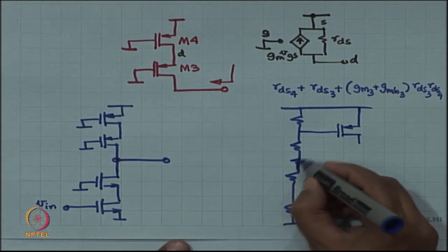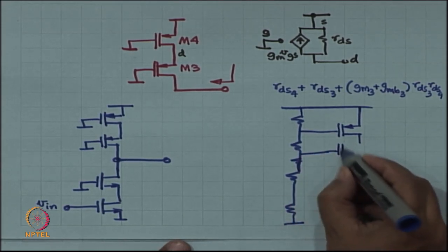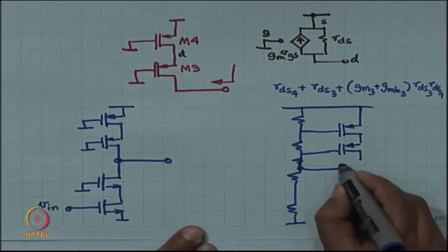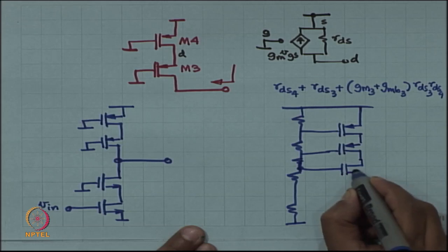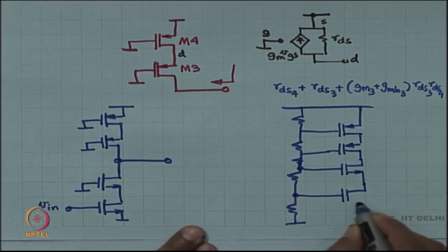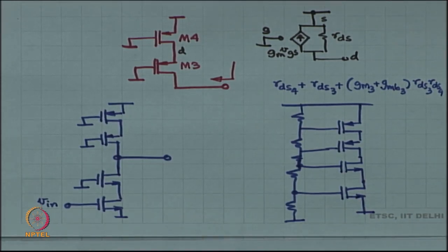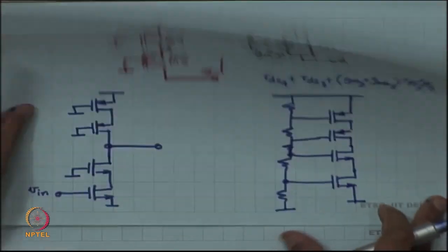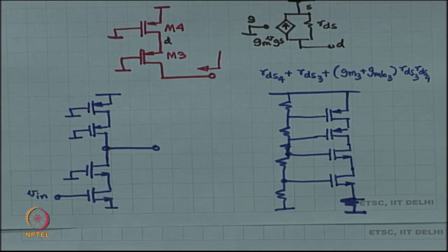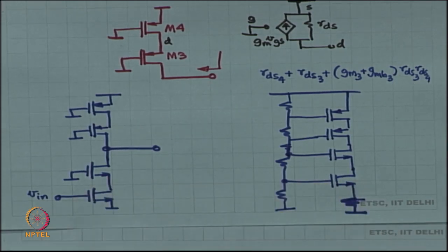You need one more resistor. Okay. You want to have a source degeneration on the bias, okay, very good. And then in the small signal picture you want it looking exactly like this.